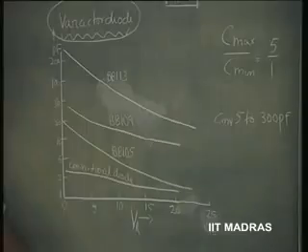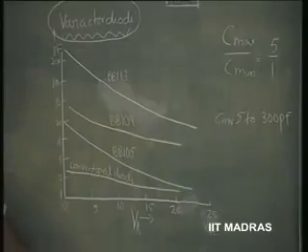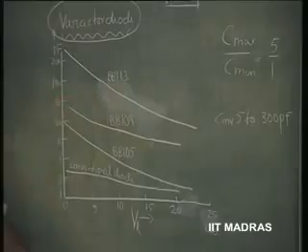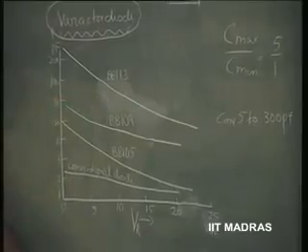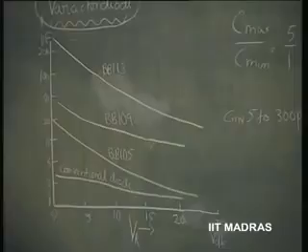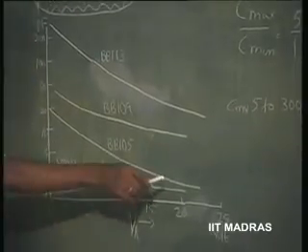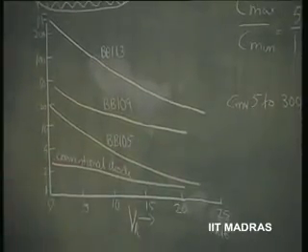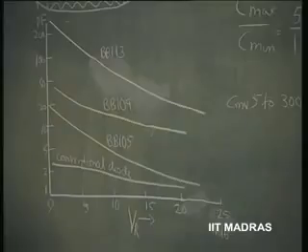minimum is not going to be significant, because it has not been manufactured for the purpose of using it for its variable capacitance. Whereas these have been specially taken care to see that the capacitance variation is maximum for the voltage that is changing from maybe 0 to 25 volts, typical change in bias voltage of these variable capacitors.